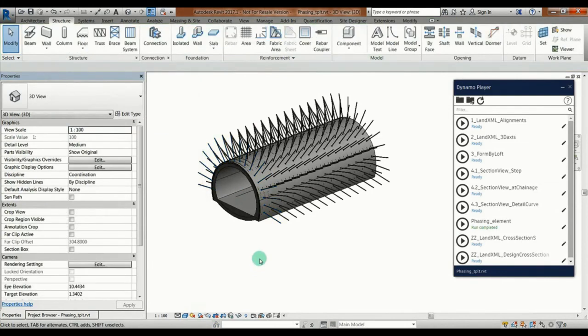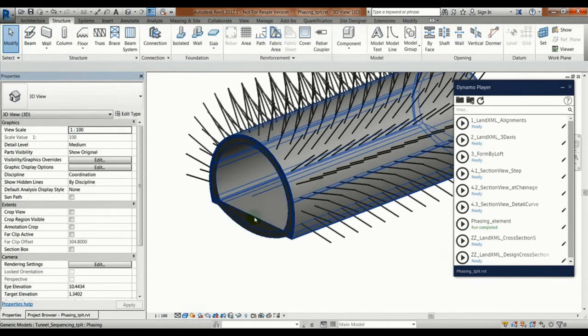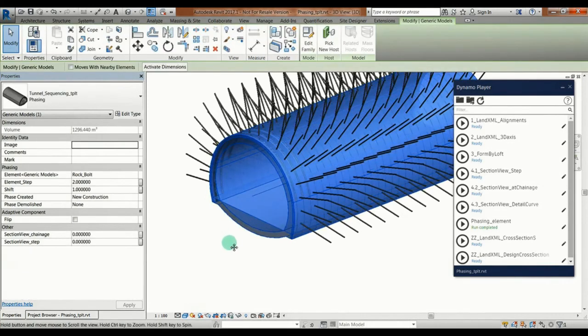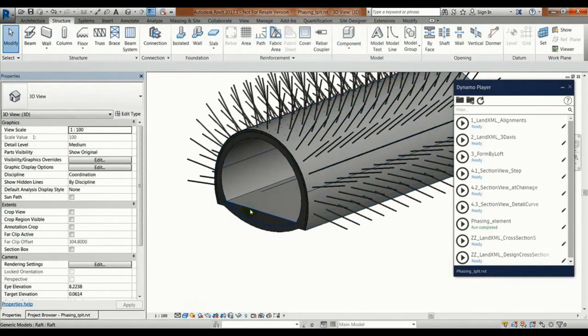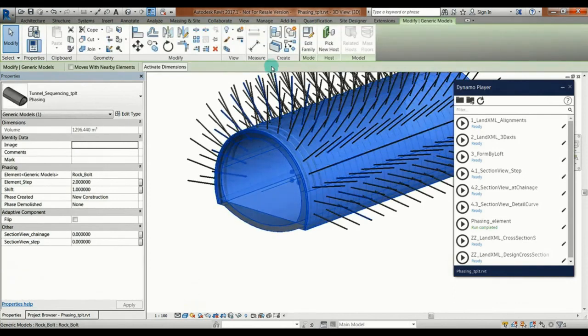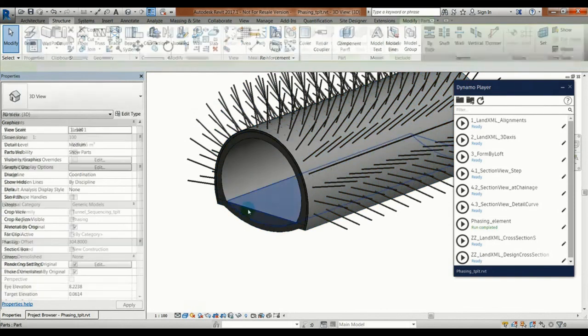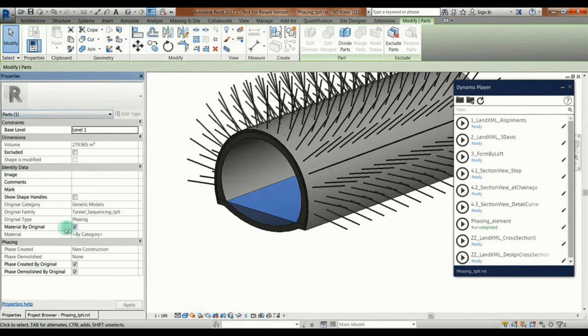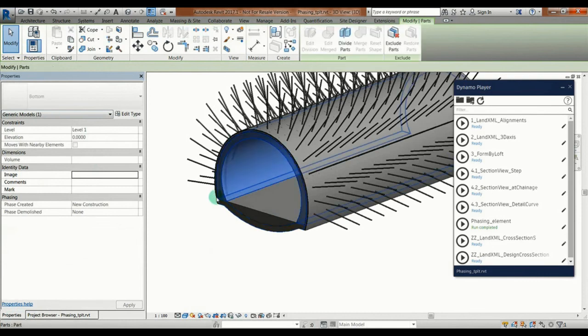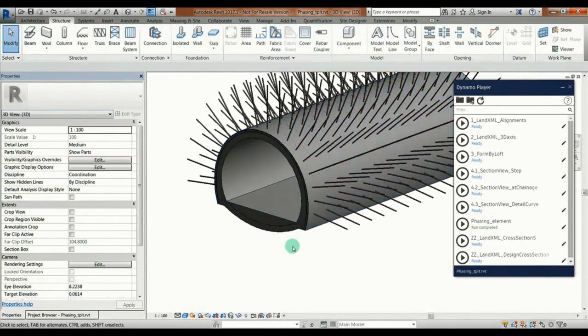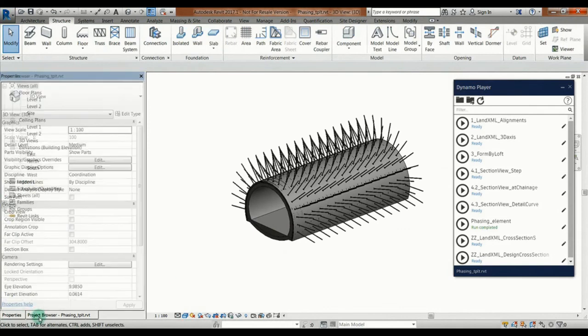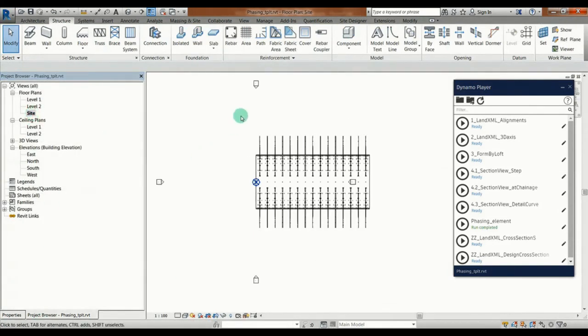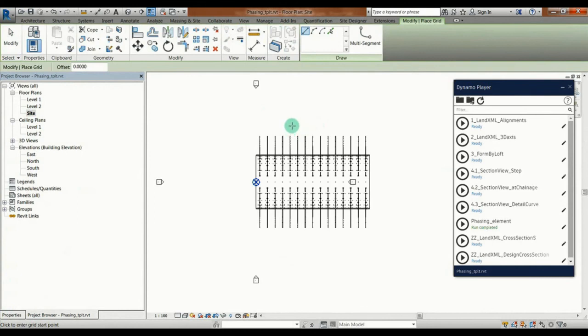And then we have to assign the phases for each of these elements. But before, we have only one block here, one big solid. So in Revit, if you just hit the Create Parts button, and because it has been created of many solids, Revit will create the parts for you. Okay, so here I've got my parts already created directly. So then I can assign for each solid a specific phase. So this is a trick: you have to create in the same family different solids per phases. So you have to think about your phases before creating a big solid.